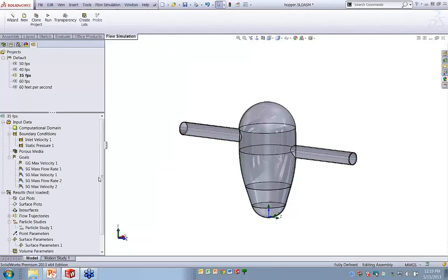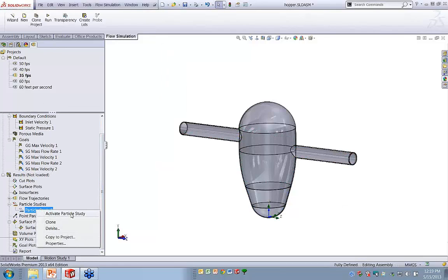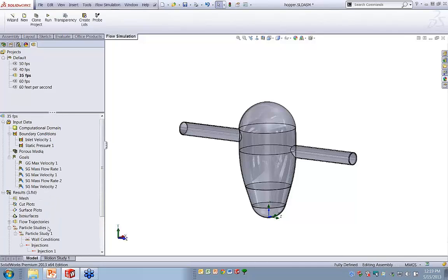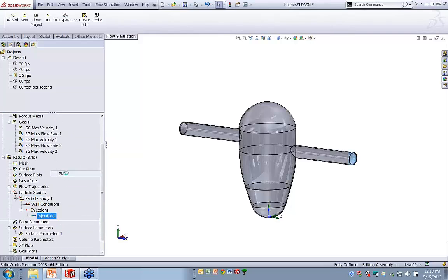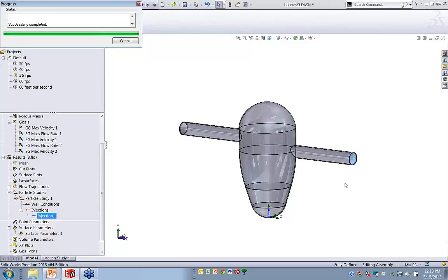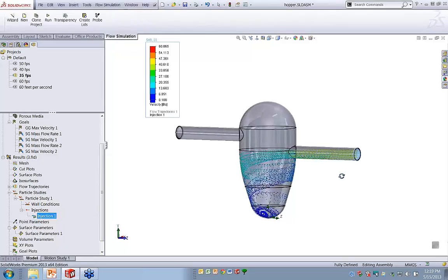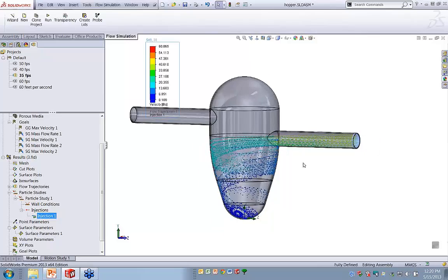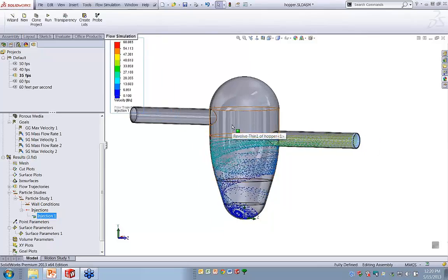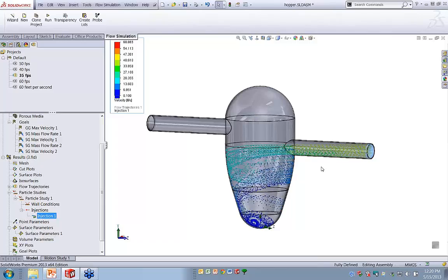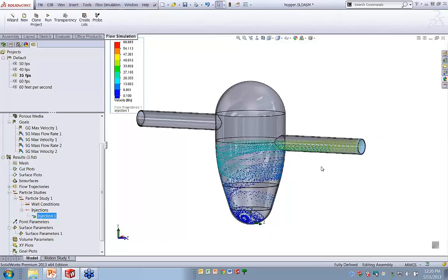So at 35 feet per second, we were now able to see nothing leaving the hopper. So when you're running this on the bench or actually in service, we know that 35 feet per second, based on the particle size, is going to be kind of that butter zone to make sure that none of the particles escape and they all settle in the hopper, and we essentially have pretty clean air coming out the outlet before it hits the filter.